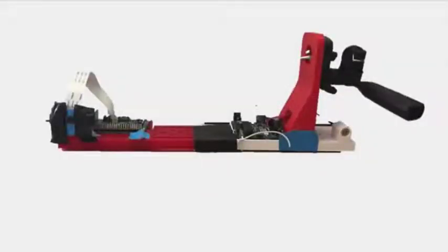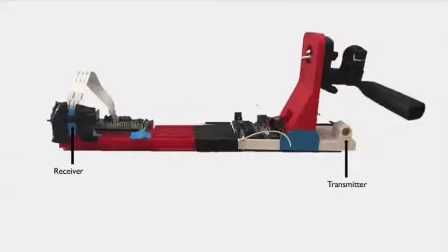Here you can see the Lidar sensor used during the scanning. All components were attached to a 3D printed rigid mount. On the right side of the sensor is the line laser, which is the transmitter of the system. When powered from the connected Arduino, the laser emits a red line. On the opposite side of the mount is the Raspberry Pi camera, which is the receiver of the system.